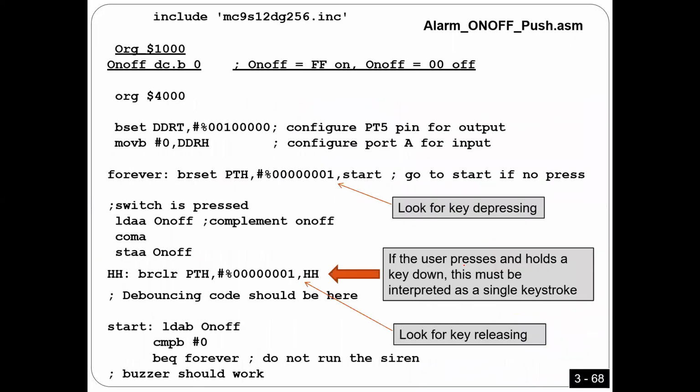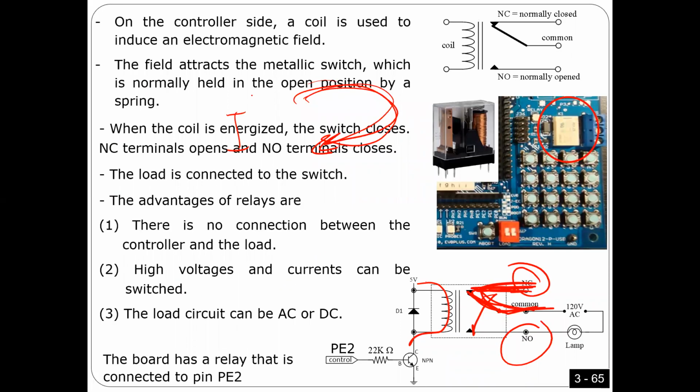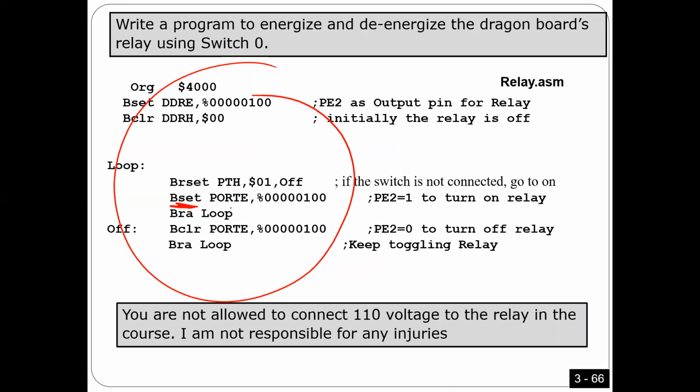Okay, guys. So here I just gave you a simple explanation. Now, how can you program it on our board? It's very easy. You have just one pin, we call it PE2. You have to configure this pin as output, that's it. And then if you want to energize the coil, just put 5 volts here. So just one pin, output 1 on this pin, very easy, right? If you want to de-energize the coil, just put 0, okay? That's why you can see here bit set, Port E, pin 2, right? So this is if you want to put 1. If you want to put 0, you can just bit clear this way. Any questions, guys?